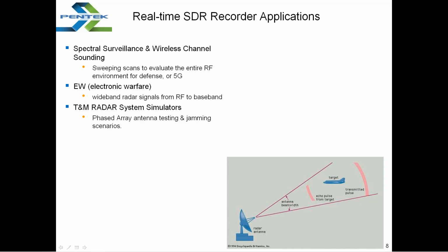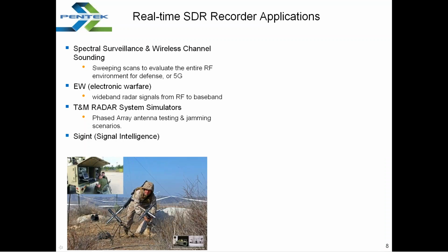Test and measurement equipment people sometimes make radar system simulators. So let's say you're testing a phased array antenna and you want to see how resistant it is to jamming, per se. You might want to record some scenario so you can take it back to your laboratory for experimentation.